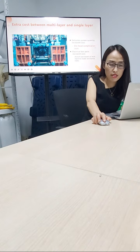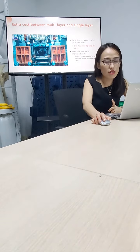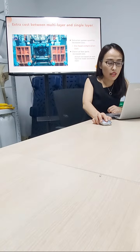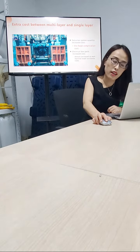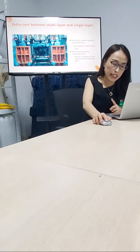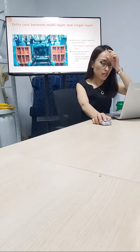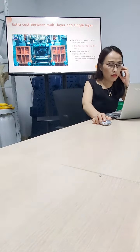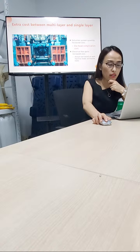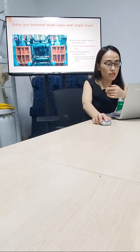First, the extrusion system increases cost, because each layer needs one extrusion system. The second is die head complication cost. This one has a big cost increase. The third is increased cost of electrical box parts, because it needs more solid state relays, switches, etc. But anyway, the actual cost should be based on each machine model and bottle size.